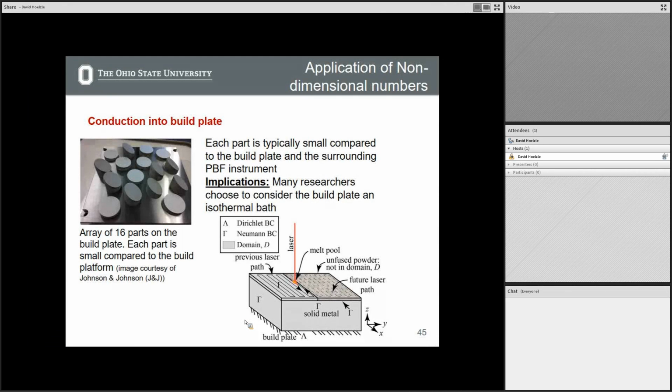All right. In terms of boundary conditions, we've defined some thus far. The order's not so great here, but before we looked at these and we said that we have essentially a Neumann boundary condition at the edges here. By saying that we have essentially no convective heat transfer into the environment, and that radiative heat transfer may not be too important, we can somewhat say that there should be a Neumann boundary condition on this top surface as well. So there's no heat transfer into the environment above.